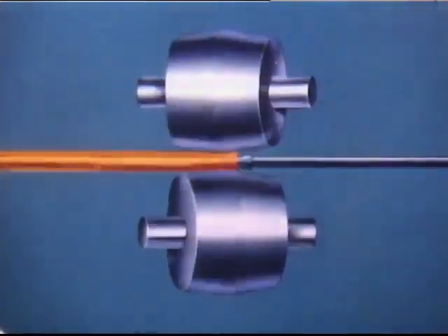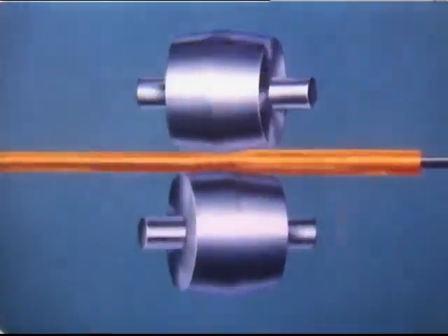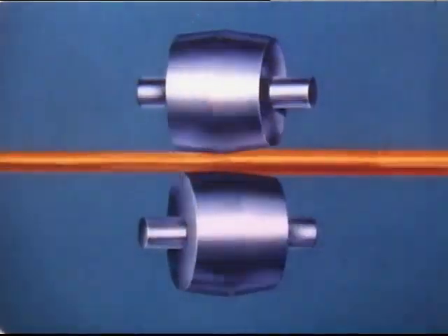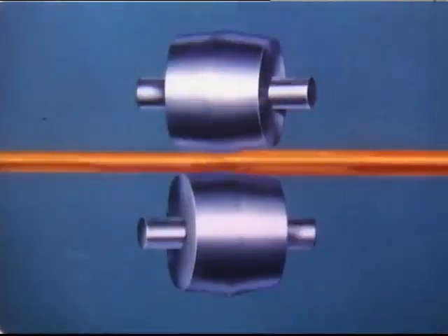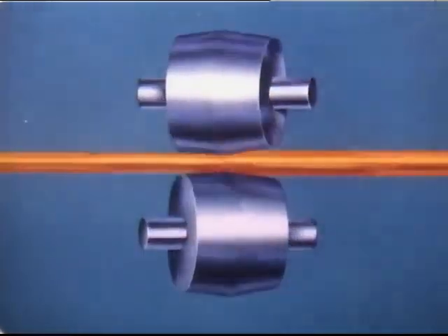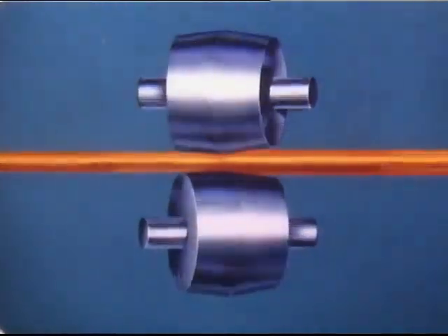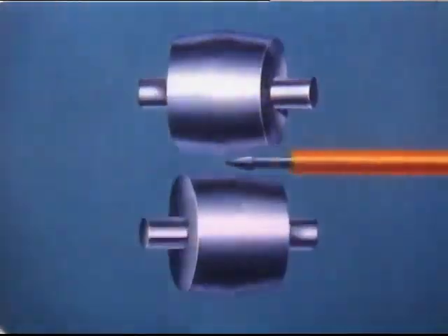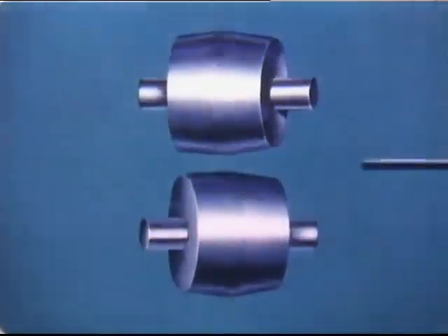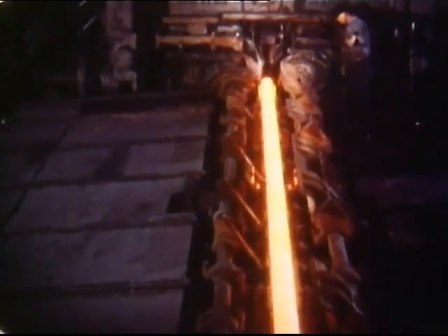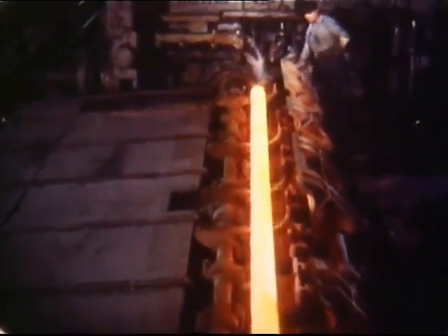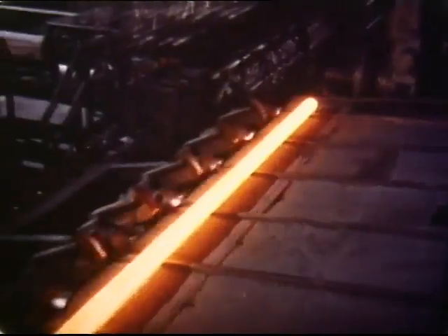When the billet is pushed into the piercing mill, the rolls take hold of it and advance it and rotate it over the piercer point. The powerful pulling and rotating action of the mill causes the metal to flow over the piercer point, with the result that the pierced round slides over the bar like a sleeve over your arm. This combined action of the rolls and piercer point form the hole in the center and throughout the length of the billet. The pierced shell, still at a soft forging temperature, is now ready for its run through the continuous mill, the first continuous seamless pipe mill in the world.